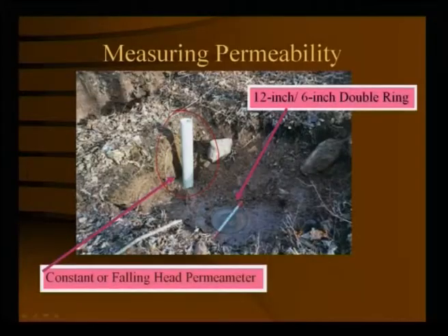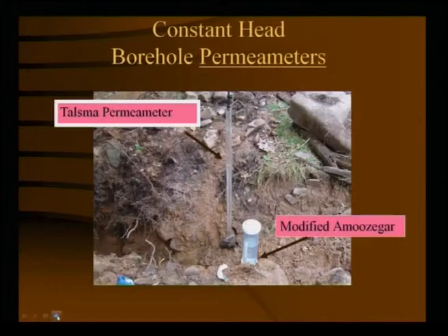Once a constant head is achieved, that means delta H by delta L amount of soil that you are considering inside this borehole. With time you can find out your coefficient of permeability in situ, vertically as well as laterally. Another one is a different permeameter.